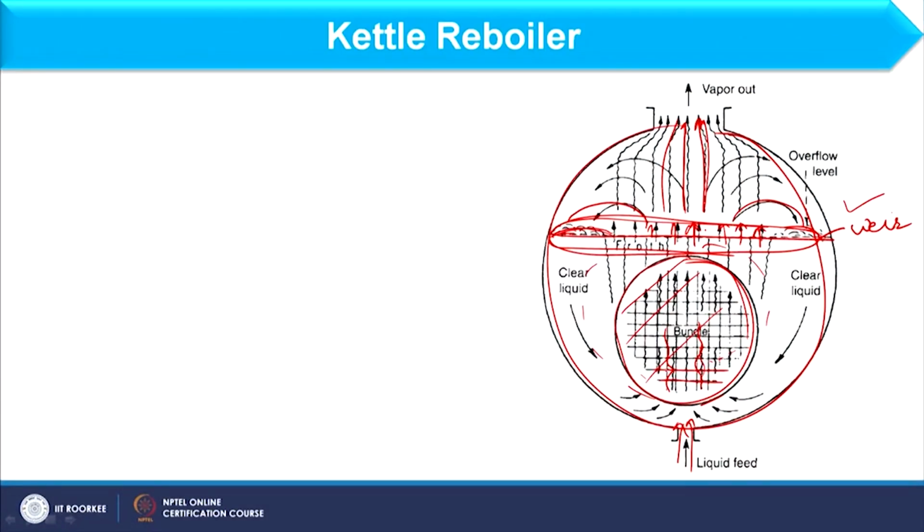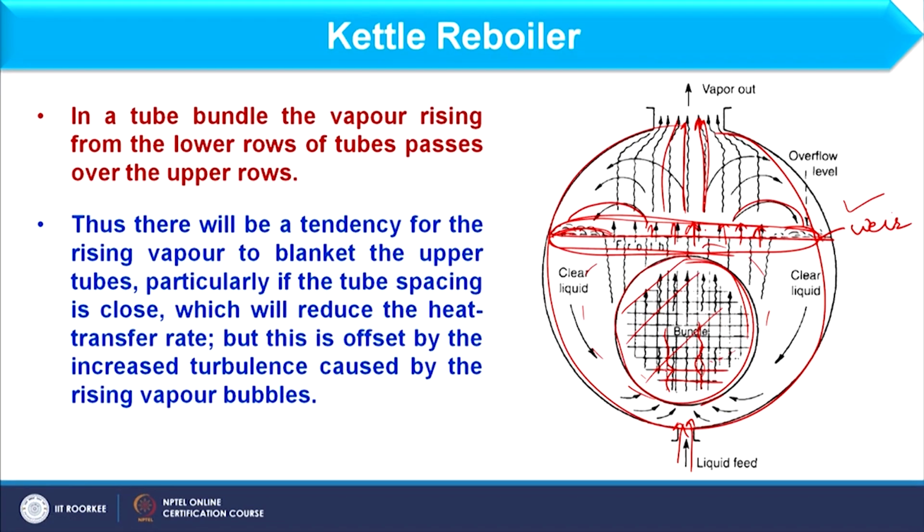So, as far as the design of the reboiler is concerned, we have to keep in mind all these points like the bundle, weir, distillation, and shell diameter. Okay. So, in this way we can understand that the mechanism of the kettle reboiler, as far as boiling is concerned, is not easy. Okay. And we have to start now the design procedure for the kettle reboiler.